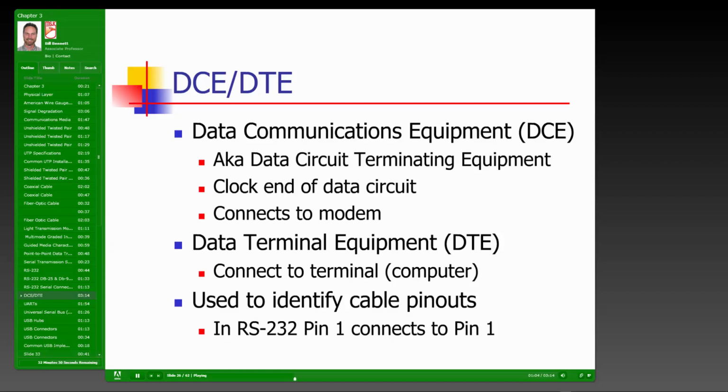So the two devices, on both ends of the communication, have to agree to what that frequency rate is going to be, because if they're operating at two different frequency rates, then one machine could send, say, two 1s in the time that another machine thinks that it's only received one bit, one 1.